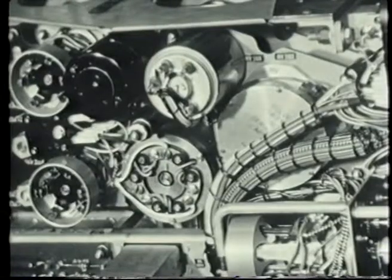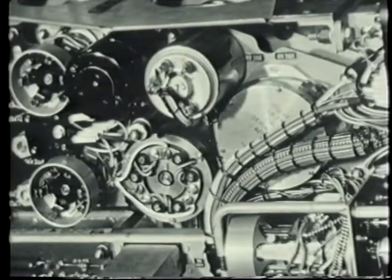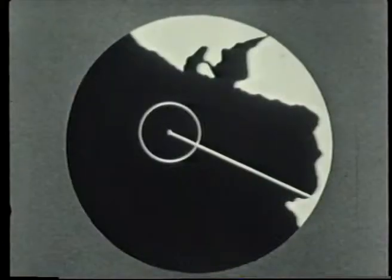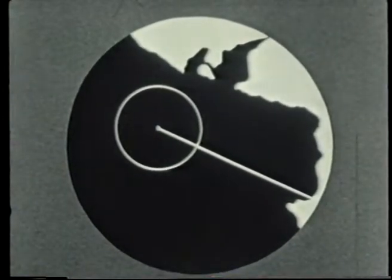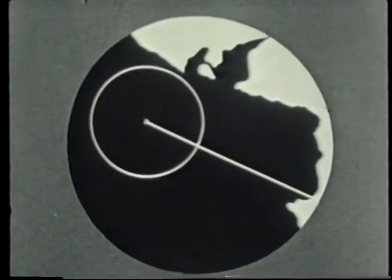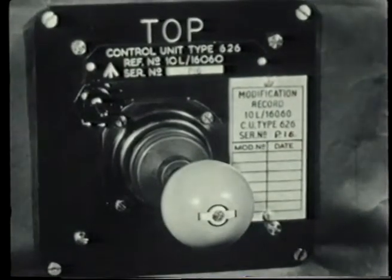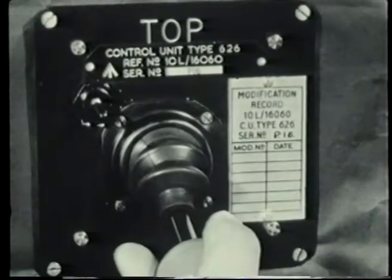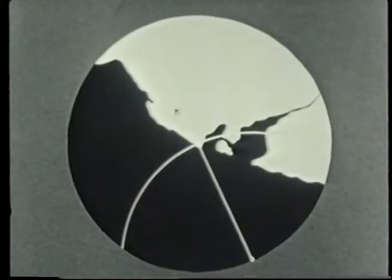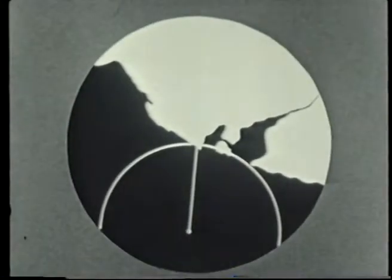It is available on all positions of the function switch other than normal. The shift currents are obtained through two shift potentiometers driven by the same shafts as the marker potentiometers. The markers vary continuously so that their intersection remains near the center of the display. Movement of the joystick now moves the whole picture so that any selected radar response may be placed under the marker intersection which remains near the center of the display. The pivot point traces out the path of the aircraft.